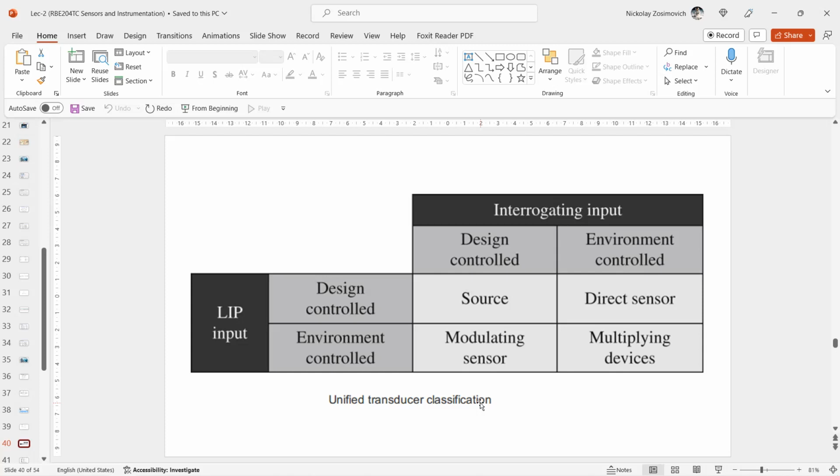First of all, it's a strain gauge bridge. Very classical explanation. Strain alters the resistance of the strain gauges. A bridge voltage converts this resistance change into output voltage. Don't worry, all of these will be discussed in later lectures.